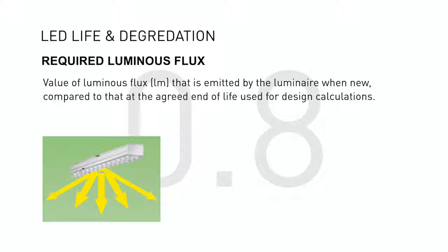When doing lighting calculations, we have to look at the light that is required to do the task, and we need to make sure that this is still met after a specific period of time. The trouble with having very long lifetimes is that we have to allow for the degradation over that period of time. This means that we are overlighting on day one so that we can reach the required levels on the last day, which is the function of the maintenance factor.